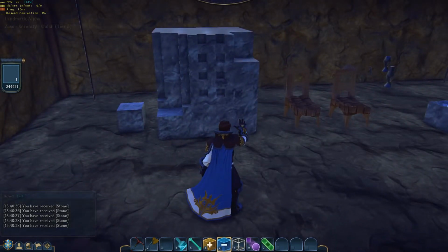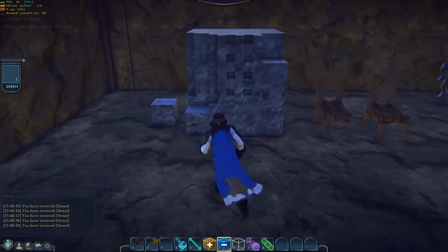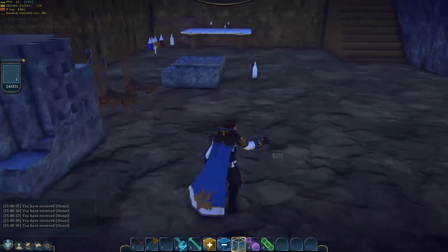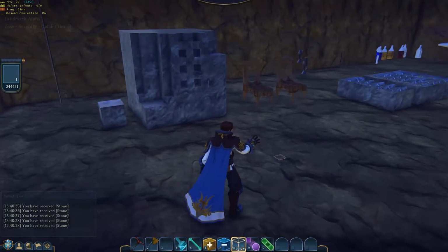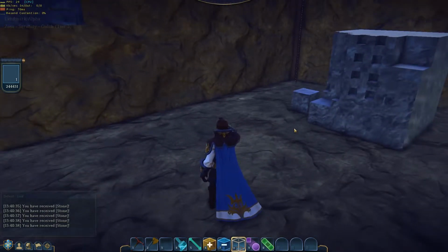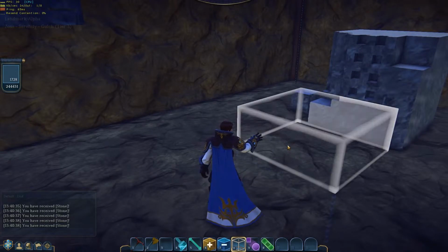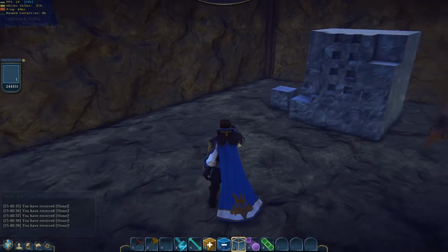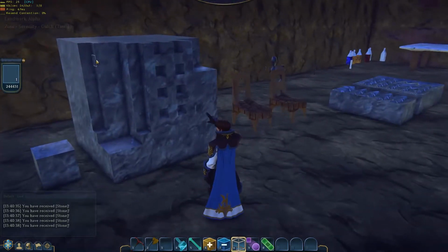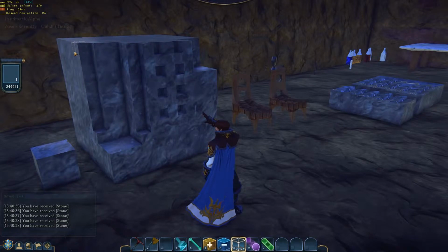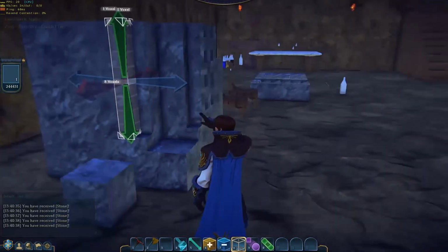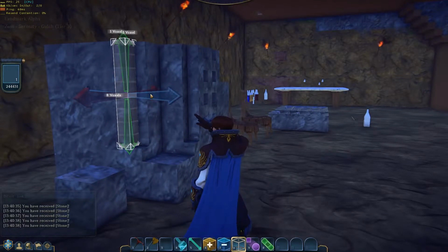The thing you really want to do to build stuff is get and use the selection tool. It's a little weird at first, but once you get the hang of it, this is your best friend. So the selection tool first allows you to select, and also you can do it in multiple sizes, but I almost always work at the single voxel size, and I'll show you why. So what I can do then is I can just select some voxels. You usually want to select just a few at a time, because you get these movement arrows, which is kind of cool.